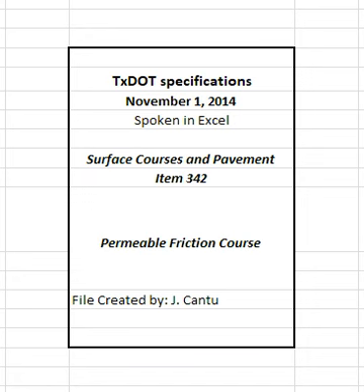2.6 Recycled materials. Use of RAP and RAS is permitted unless otherwise shown on the plans. Do not exceed the maximum allowable percentages of RAP and RAS shown in Table 2. The allowable percentages shown in Table 2 may be decreased or increased when shown on the plans. Determine asphalt binder content and gradation of the RAP and RAS stockpiles for mixture design purposes in accordance with TEX-236-F. The engineer may verify the asphalt binder content of the stockpiles at any time during production. Perform other tests on RAP and RAS when shown on the plans.